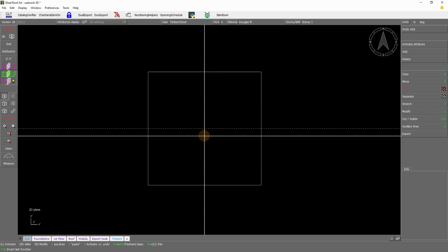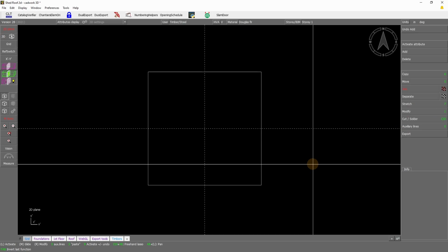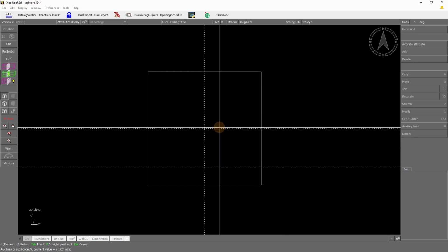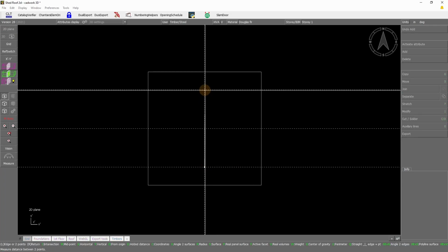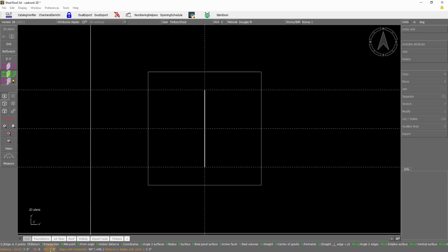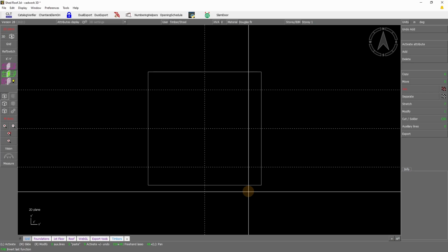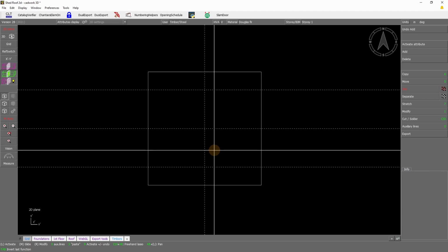The steel shape that we need to add is 1 feet and 3 inches long. So again, E for auxiliary line with offset 1 feet 3 divided by 2, and click on the top and at the bottom. So here again we can make sure that this is correct by measuring. So we do have 1 feet and 3 inches. So that's perfect.